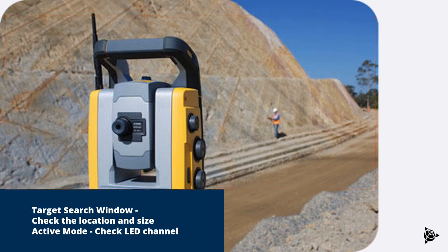On the other hand, when you define this window, make sure that it's not too small so that you're not within the window. Ideally, you want to define the upper and lower extents of your window so that you're fully enclosed within it and it won't take long to find the prism. If you're using active mode, check the LED channel to make sure it's correct and matching the total station. Otherwise, during the total station search, it will pass over the prism altogether.